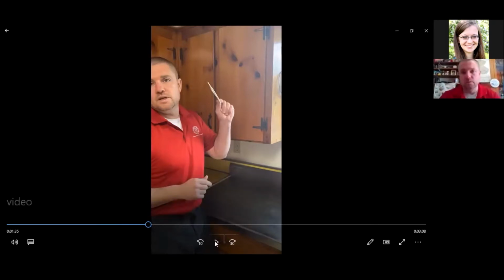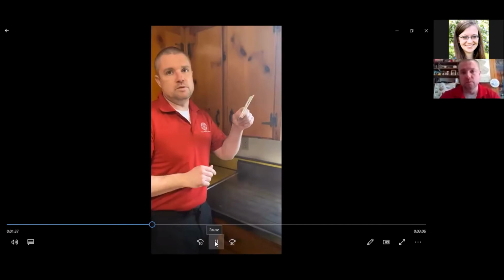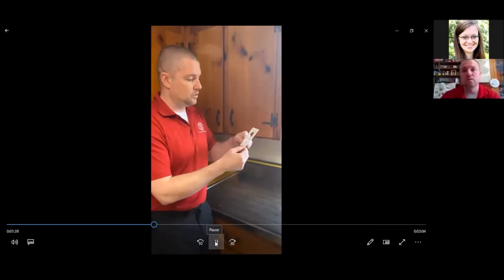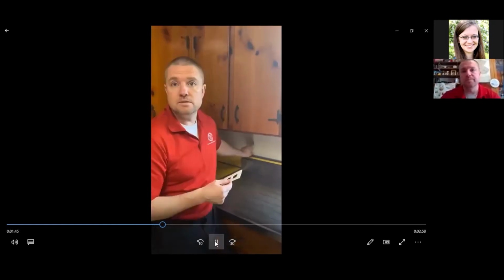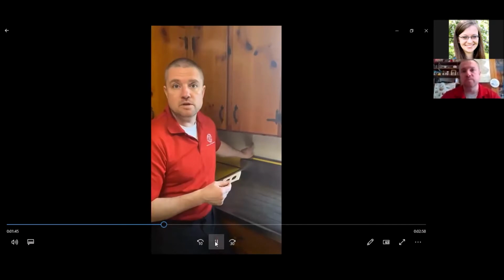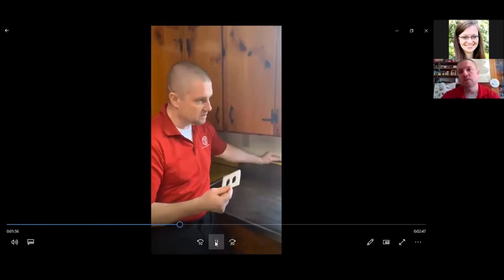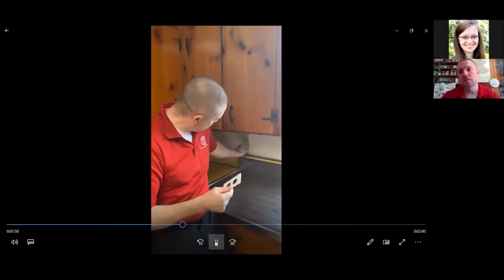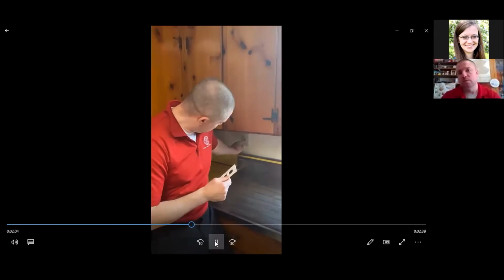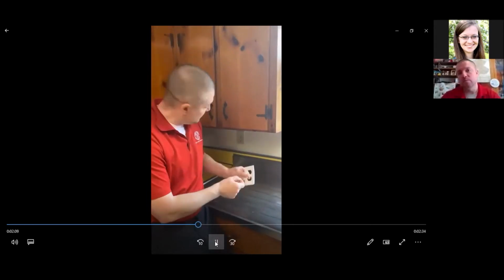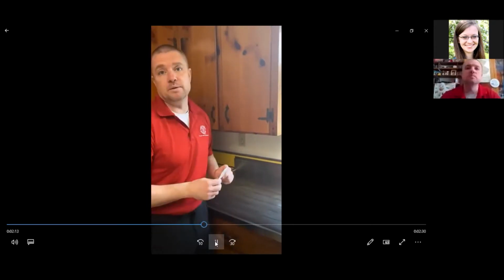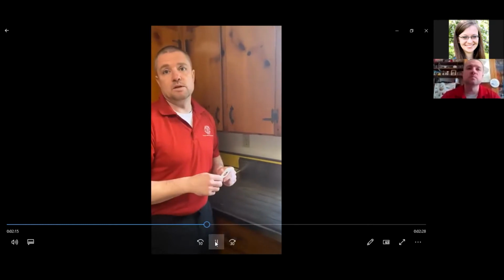Gaskets. You can find these at home improvement stores, online I'm sure as well. But this is really simple to install. These are usually uninsulated behind the outlet switch plate. You only need to worry about this on your exterior walls. You don't need to do it on the inside of the house because that's not typically insulated. So I would just turn the power off, or your main circuit breaker. Unscrew this, pop this hole out in here, and then put it behind the plate and put the plate back on. Real simple, and that would reduce your airflow through that space.